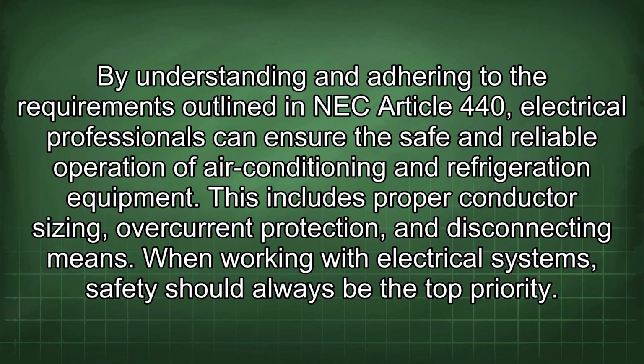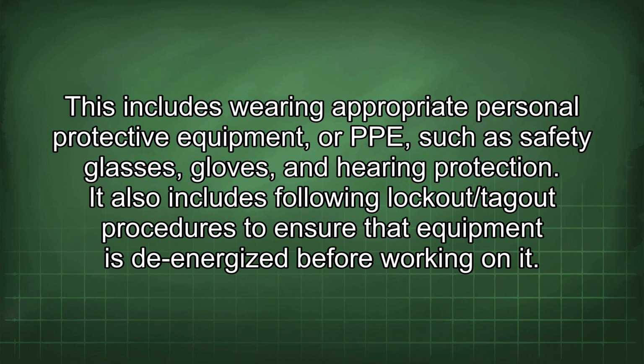When working with electrical systems, safety should always be the top priority. This includes wearing appropriate personal protective equipment, or PPE, such as safety glasses, gloves, and hearing protection. It also includes following lockout/tagout procedures to ensure that equipment is de-energized before working on it.